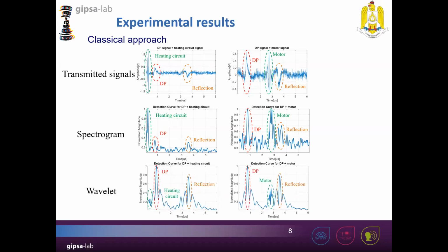Using the wavelet approach, by determining the detection curve, the existence of local maxima can lead to false detection. Not knowing the shape and size of the signal, there are problems given the choice of wavelet. And in this case, a visual evaluation is needed. There is also the problem related to setting the detection threshold.